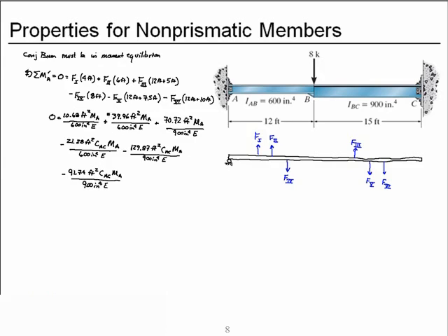So I'll amplify each of the numerators here by 1.5. And if I consolidate these terms, again needing to convert this one, we get 0 equals 146.68 feet squared, moment at A, over 900 inches to the fourth E, minus 253.53 feet squared, carryover factor, moment at A, over 900 inches to the fourth E. And that is our second equation.